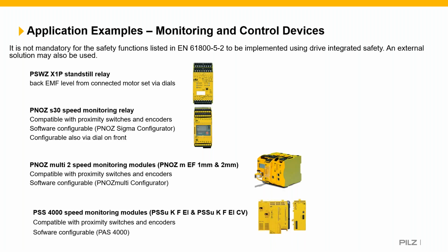So in this case, we've got standstill relays. In particular, back EMF is a good way of monitoring standstill. It's non-invasive. There are no sensors required other than just monitoring the voltage. So that's really quite a good, easy way of monitoring for standstill.